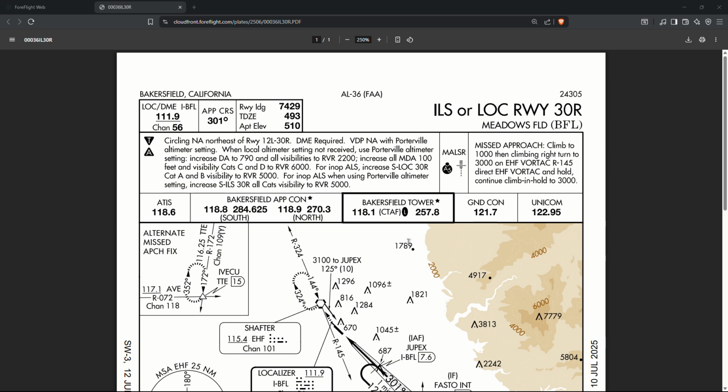airport elevation. Those matter because for landing larger aircraft, we want to be able to have the best chances of landing, and on a smaller runway that has a downslope, you're not going to be able to get as much traction when you're braking. You're going down with gravity, so you're not slowing down as you would on an upslope, and that could change a landing from a go to a no-go.